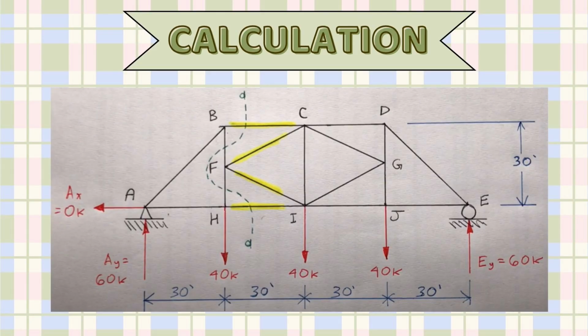The general steps for calculating the load on each member are: first, verify the stability and determinacy of the structure. Second, determine the support reactions in the truss. Next, identify the zero force members in the system. Fourth, cut the truss into two sections by passing a section line through the members whose forces are to be determined.